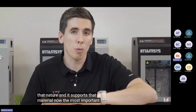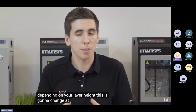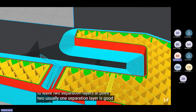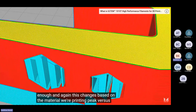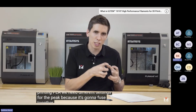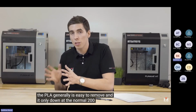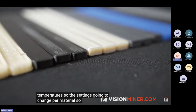Now, the most important part of supports is your interface layers. Depending on your layer height, this is going to change. At 0.1, you might want to leave 2 separation layers. At 0.2, usually 1 separation layer is good enough. And again, this changes based on the material. If we're printing PEEK versus printing PLA, we need different settings for the PEEK because it's going to fuse together. It's 400 Celsius, and the PLA generally is easy to remove and you're only down at the normal 200 Celsius temperatures. So the settings are going to change per material.